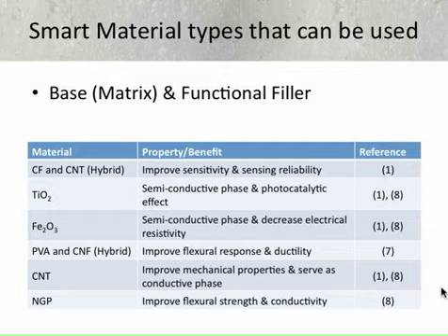Nanoparticles in powder form, such as nanoiron, have been widely utilized in cement and concrete. We can also see that hybrids exist where a combination of material forms is used. Here the fibers are mixed with nanotubes to improve the sensitivity and also the sensing reliability. And NGP at the bottom here are carbon-based conductive nanoparticles made from graphite.